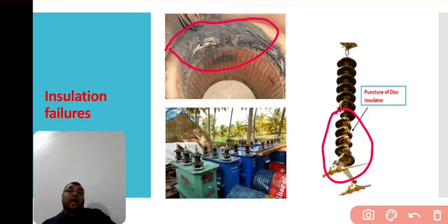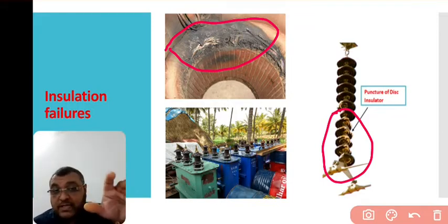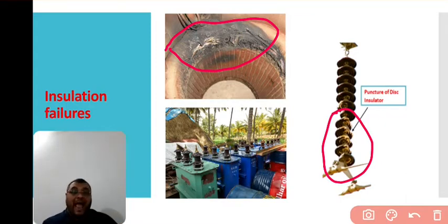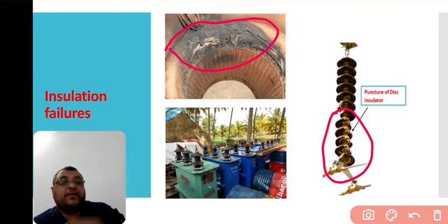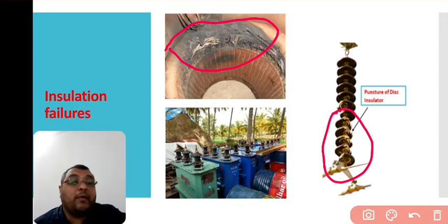Okay, and when this puncture happens, what it causes is that the transitory overpotential stresses the molecular structure of the insulating material. It gives a burden of stress to the molecular structure of that insulating material. That's why it is going to be damaged. You can easily see that in the picture. It also causes ionization and failure of the insulating material itself. Okay, so the electrical stresses will be more significant with high voltage apparatus or equipment exposed to voltage transients. You can easily see the effects when a high voltage transient attacks those electrical equipments.